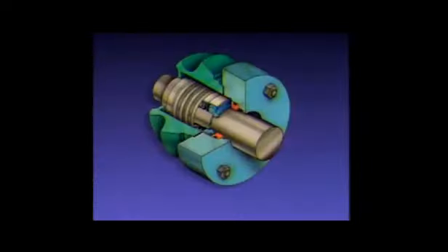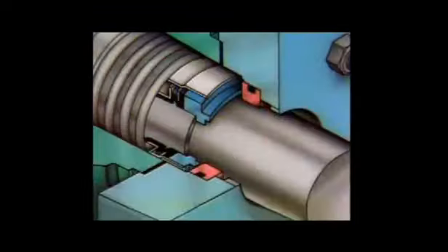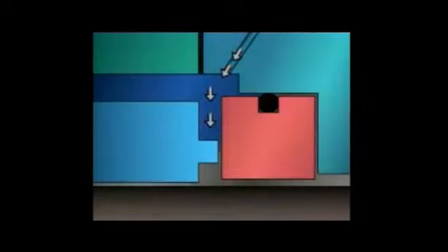A mechanical seal has two elements: a stationary element and a rotating element. Each element has a seal ring. The seal rings mate together to form a nearly perfect seal that has virtually no leak-off. To prevent the seal rings from drying out, overheating, and becoming damaged, some type of lubricant must be supplied to the seal rings. In some applications, the liquid being pumped is used as the lubricant. However, if the liquid being pumped contains abrasives or would be hazardous if the seal failed, an external source of clean liquid may be used to lubricate the seal rings.